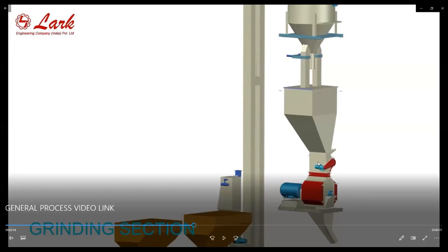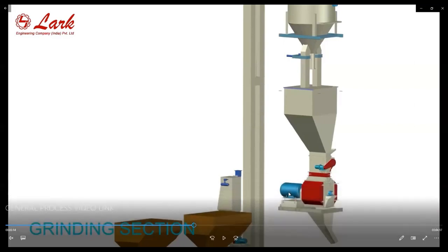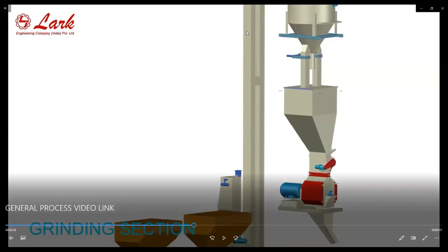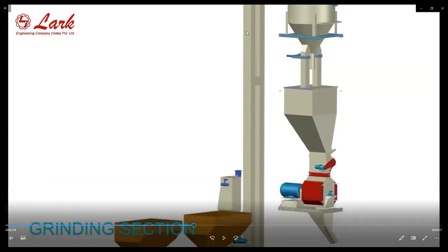This rotary vane feeder motor is synchronized with the main motor of the hammer mill with the help of the VFD. For example, the power of the hammer mill is around 75 HP in a 5-ton feed mill, or 150 HP in a 10-ton feed mill, and the ideal amperes of a 150 HP hammer mill is around 180 amperes, as the motor is of 2800 RPM.